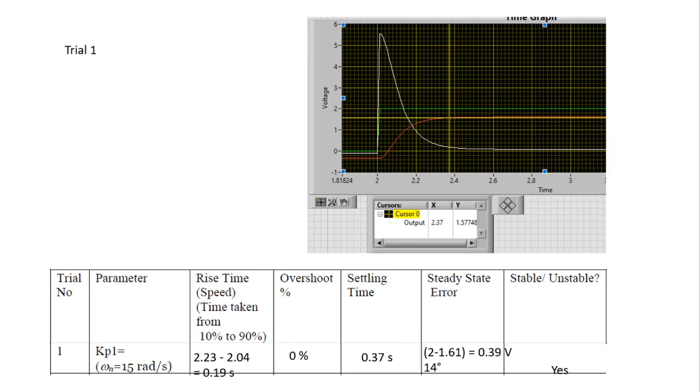In an unstable system, it keeps asking for bigger and bigger voltage input, like this white line right there. It's going to keep going up until I put a physical limit, a ceiling on that. Why? Because if your PID controller keeps asking for bigger and bigger voltage, and I keep giving it, your motor will burn out. And this has happened, I guess many times. About three times over the last maybe 6 years.